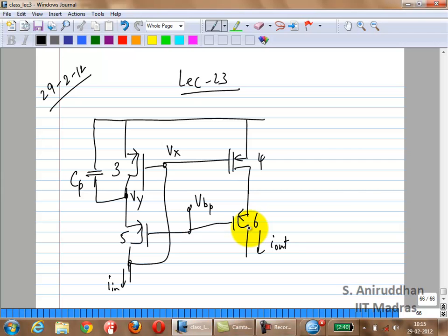So in reality, in this case, you actually have a feedback. So it's not so obvious. If you have no feedback at all, then what you say may be correct. You can find out the impedance at that node, find out the capacitance at that node, and calculate the pole position. In this particular case, you have feedback from the gate of this to the input node. So in reality, if you actually calculate the pole position, it won't be the same. It won't be just the conductance at this node over CP. Can everybody try it out?